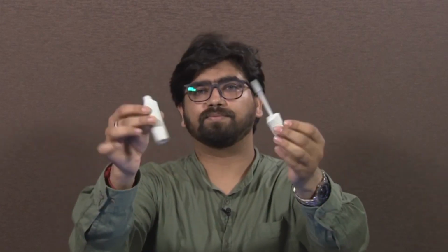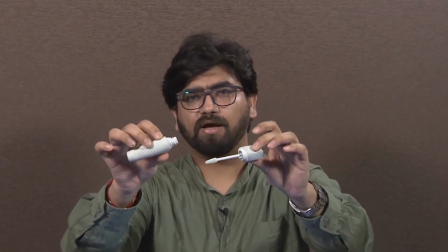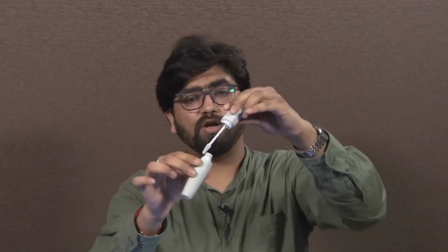This particular part was built by SLS, where the direct assembly was produced in a single go. If you open this part, you will see that it consists of two parts, and then they are assembled together through threaded joints. However, the portion where the material is not there, some loose powder will be there, and that can be later on removed. That is how you can produce the direct assemblies through this process.